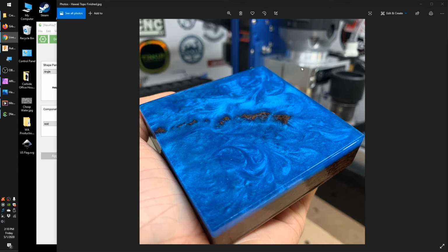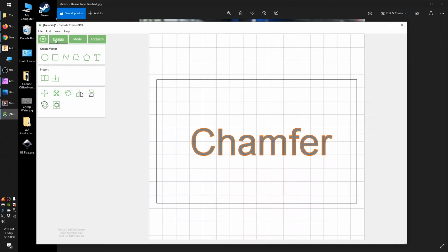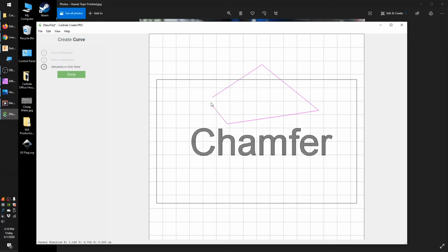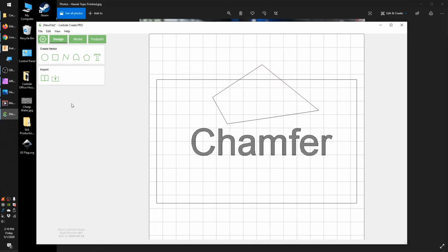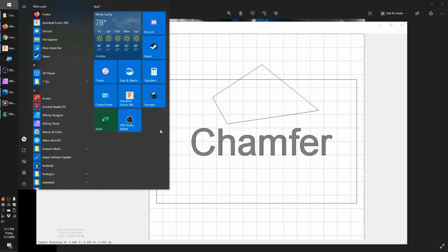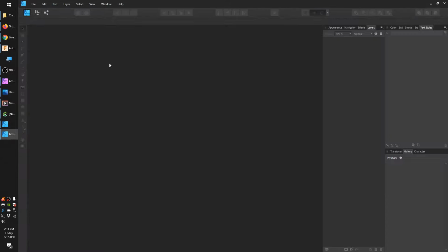And let's see, I don't think I have an example easily available, but I think you can potentially change the nodes. Let me try. If I go into node edit mode, I don't think I can change these, but in Inkscape or something, you can pick the nodes in your file and convert them from vertexes to curves. I'm going to try and pull this up in Designer just to give an example, but SVG is usually a better fit for what you see is what you get when you import it into Create.